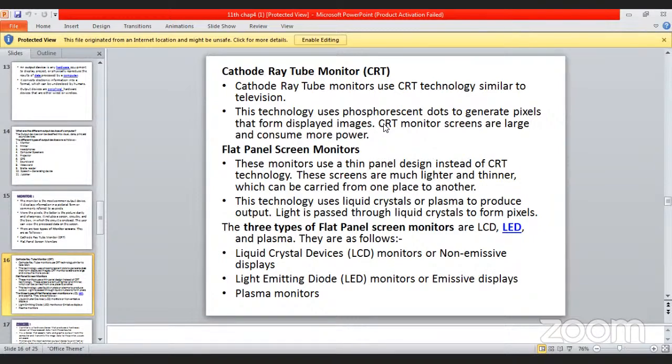In video monitors, there are some different characteristics also presented. First, we can see the video monitor characteristics. What are the different characteristics presented? First will be the dot pitch. Dot pitch means, the more resolution means more dots on a screen, and the distance between the centers of the dots on the monitor is the monitor's dot pitch, and it is measured in millimeters.